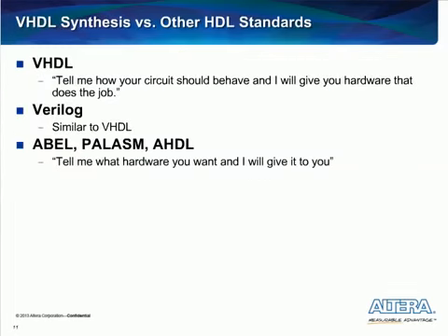Both VHDL and Verilog can be used as higher-level languages that support behavioral synthesis. Other languages like ABEL, PALASM, and AHDL are more structural. With those languages, you specifically instantiate the component you want in your design, such as a D flip-flop, and the tool goes into a library and drops that into your design. Very similar to low-level schematic entry of the old days.